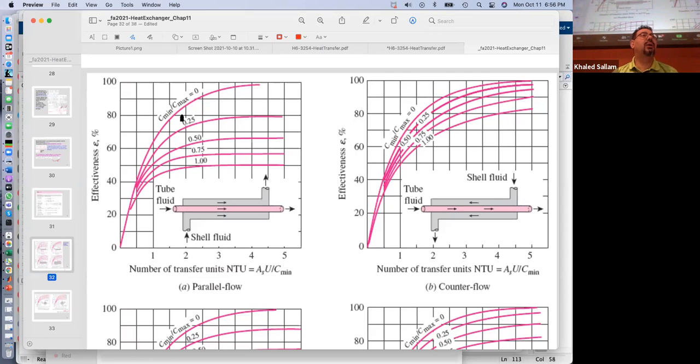So when you say Q dot for a phase change, what's Q dot? M dot h_fg. But if you want to say, no, I want m dot Cp delta T, I want to calculate it like this, I need my Cp, or my capital C, because I need to use this chart. Then in that scenario, you will have to say that my capital C is equal to infinity.